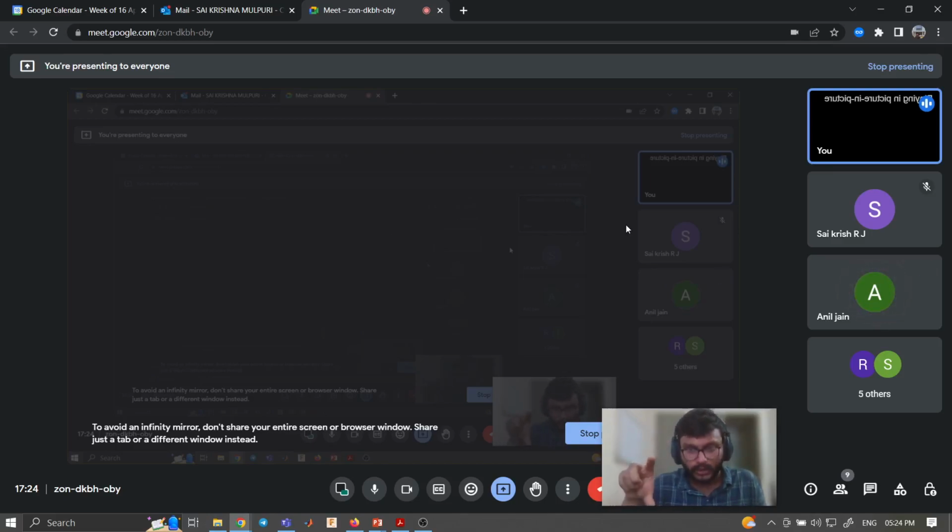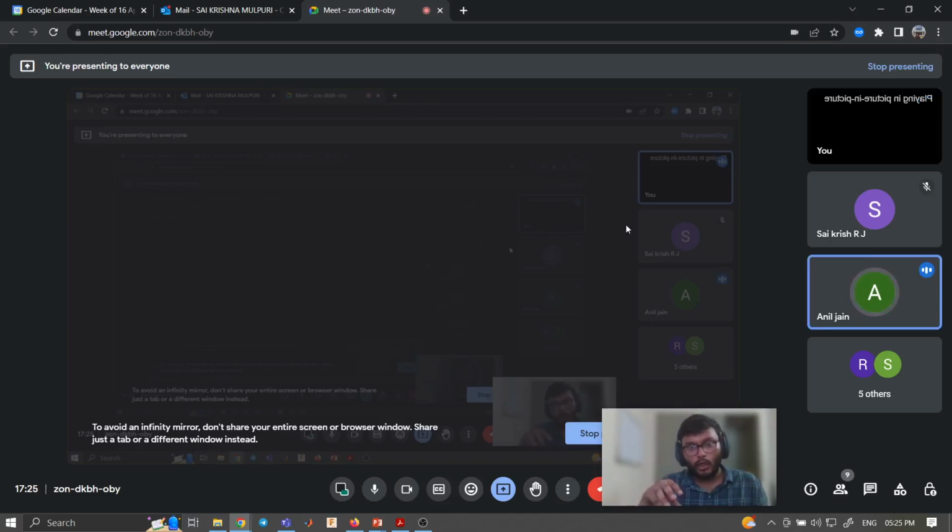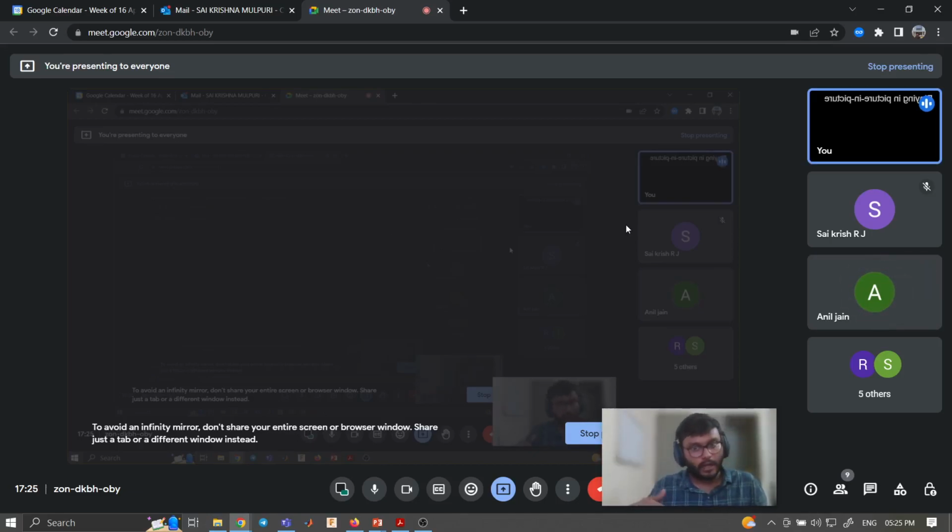But if it's a synchronous motor, whatever supply you are giving to the factory, it will just take a little bit of supply from the supply itself. You don't have to provide another mechanical prime mover rotation to it. Also, in the synchronous generator you are supplying to the bus, but here we are not giving to the grid, we are taking back from the grid such that the summation of IA and IC would give a resultant current which is close to unity power factor. So that won't work in the case of a synchronous generator.